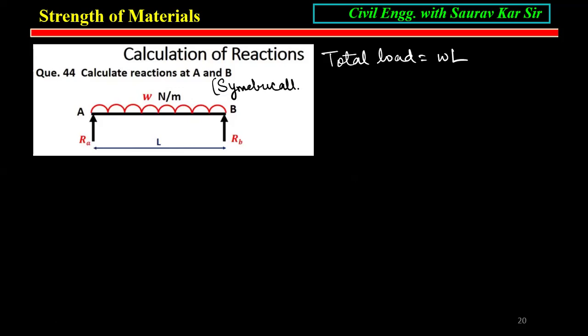distributed throughout the length. So it is a symmetrical beam. Imagine you are holding a scale with your two fingers. So UDL W, full UDL, no partial. The total load is WL. And similarly, the load is distributed between the two reactions RA and RB, WL by 2, WL by 2.